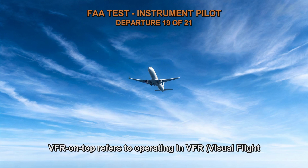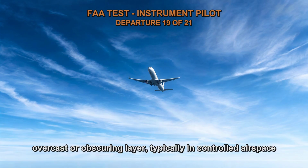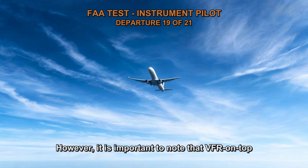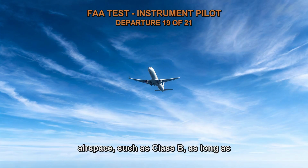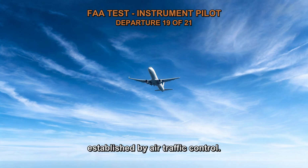VFR on top refers to operating in VFR, Visual Flight Rules, conditions while being on top of an overcast or obscuring layer, typically in controlled airspace below Class A. However, it is important to note that VFR on top operations may be permitted in other classes of airspace, such as Class B, as long as they comply with the specific requirements and procedures established by air traffic control.